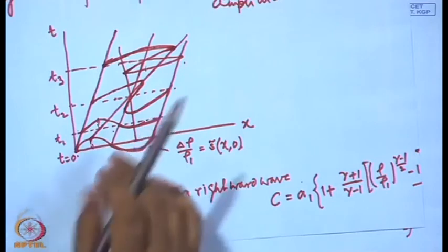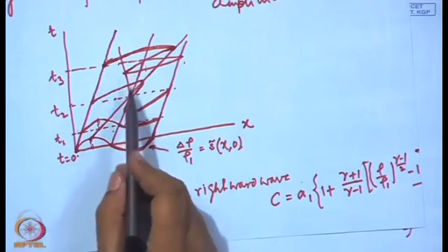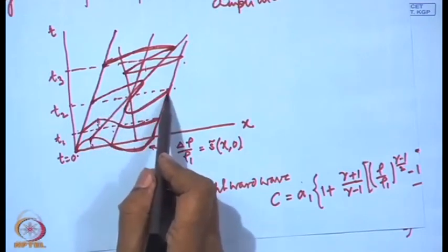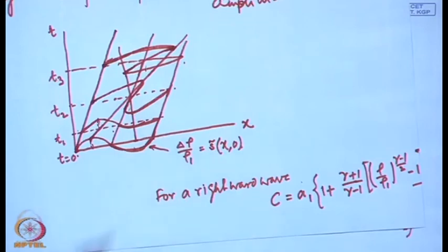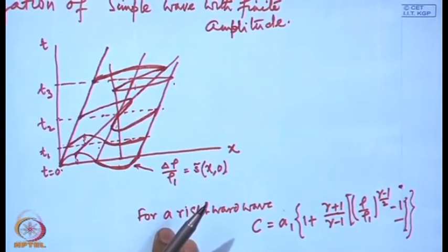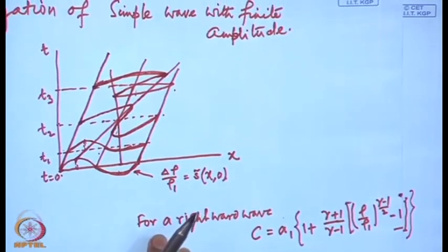The simple reason is that, considerably well before this situation occurs, the velocity and temperature gradients reach such a high value that the viscous effects and the heat transfer effects are not negligible, and the diffusive actions are considerable, and their effect will be such as to counteract this steepening tendency.